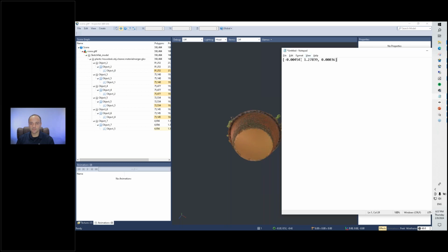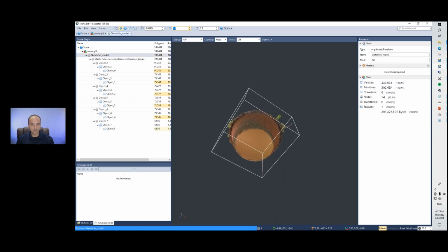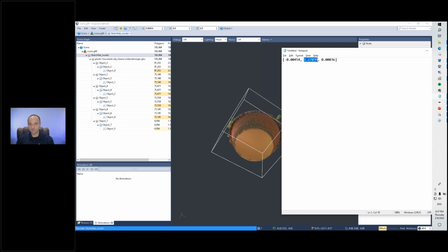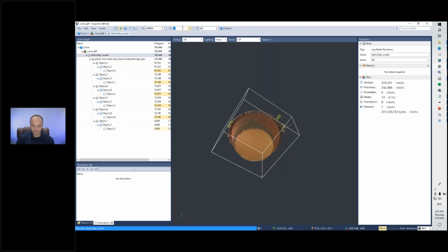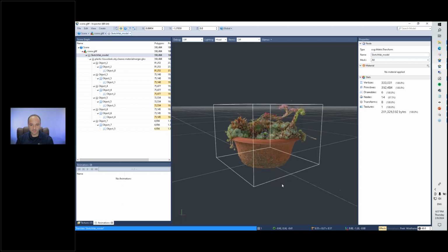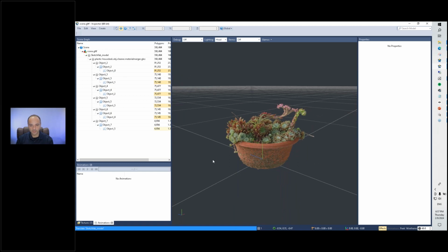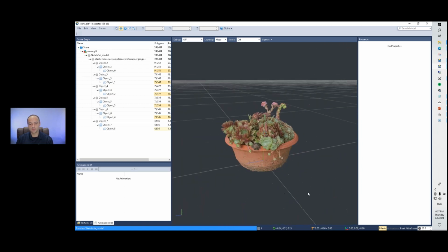So if I reverse everything, I take these values, and instead of a minus sign, I put a plus sign here and start modifying. So paste it in, okay? And then I take this one, but I take it with a minus sign, okay? And then the Z coordinate is pretty much 0, so I don't have to do anything, and press the Z key. See, now I am really truly in the middle. And if I hit F3, I can also go in wireframe mode, but you can see that it's right there. It's in the middle of the world.